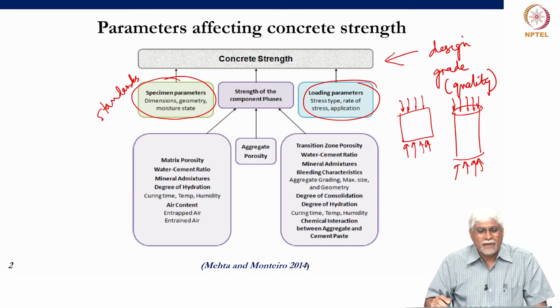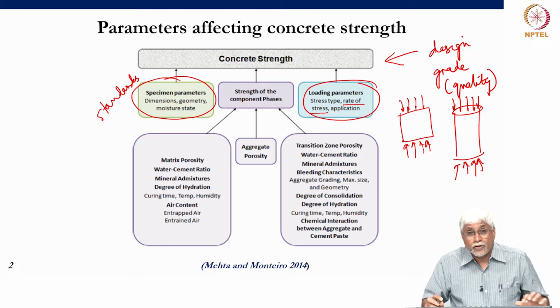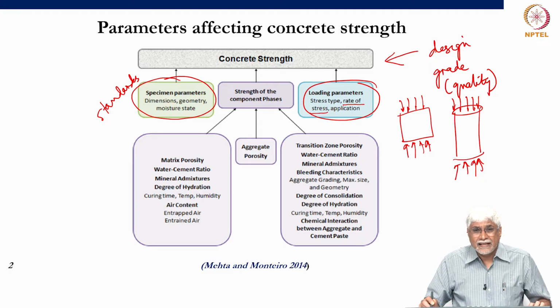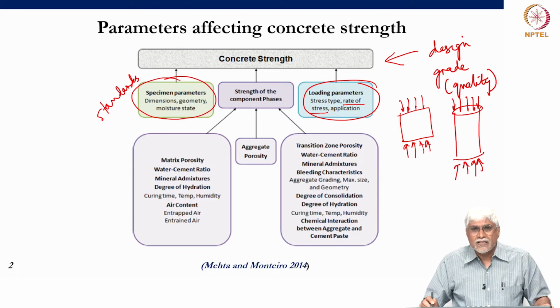This is a rule of thumb to decide what would be the rate of stress that needs to be applied during a test. When we are doing a new type of test, we often say that this is the rate of loading that should be applied. If the failure occurs in say about 3 minutes, that means the test can be considered as quasi-static.